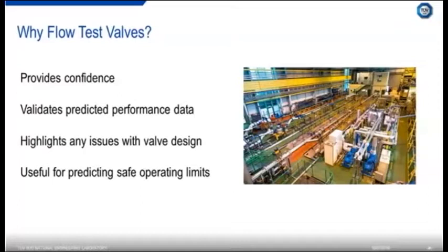Valve flow testing can also highlight any issues with the design of the valve. A lot of the time valve designers or manufacturers will come to us at the design stage to do some flow testing, to try and characterize the performance of their design. If they come across any issues in the design stage, they can rectify them before the valve's been deployed or sold, and it's much cheaper in the long run to rectify problems early on. And valve testing can also be useful for predicting safe operating limits. That's more related to the pressure recovery factor number, which is related to choked and cavitating flow.